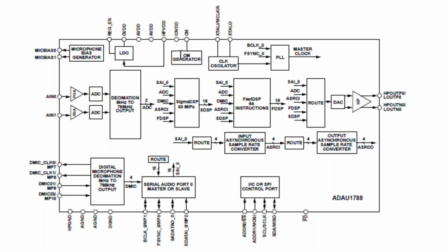As I won't be using this, I won't discuss the datasheet much, but as you can see, it has a bias generator for electret microphones. It has 2 inputs, so like left and right, going through the ADCs, and I2C or SPI control ports, and it has a single output.